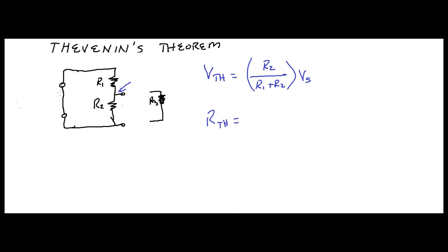We're assuming it's 0. And now, what is the resistance at this point in ground? What's the resistance going to be? Well, R1 and R2 are in parallel at this point, aren't they? So it's simply going to be R1 in parallel with R2, right?